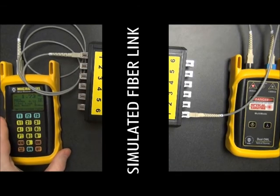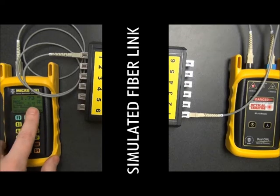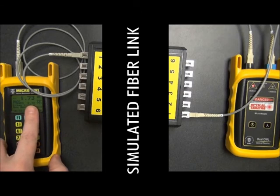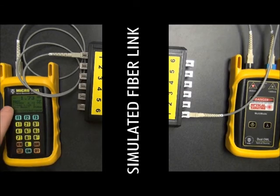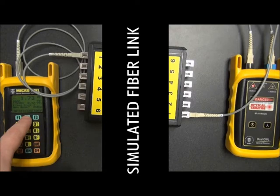If you can see that here, it says 1.73 or negative 1.73. That means that you have 1.73 dB of loss, but you're still passing by almost 3/4 of a dB. As you can see, there's a pass reading. That's good. So what we need to do is we need to store the reading here. So we press the F2 button to begin the store process.